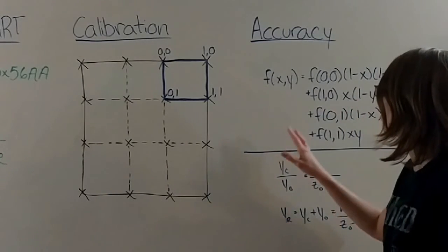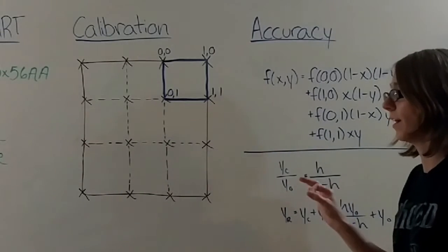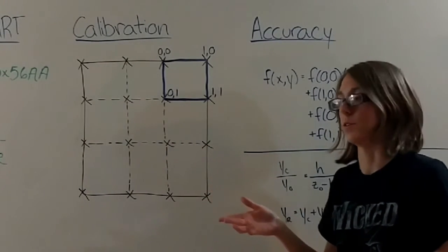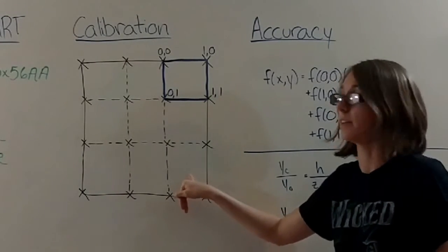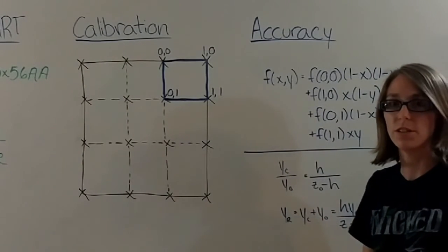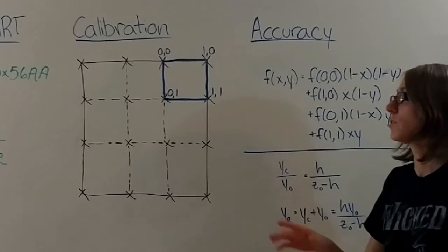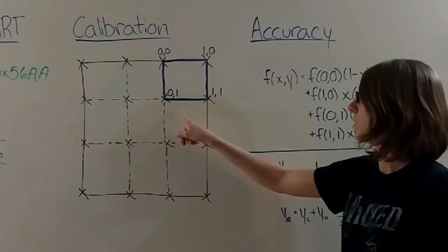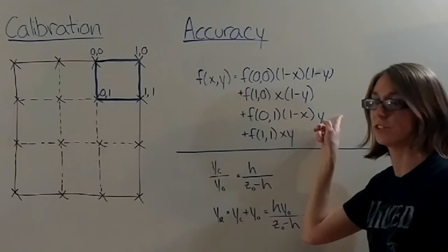Next, I use an algorithm to determine which block an object is in. So if an obstacle is in this block, then it's in block 9. The reason why this is useful is because I use bilinear interpolation, and that uses a unit square. So this is what a unit square looks like. It's (0, 0), (1, 0), (0, 1), and (1, 1). And this is the bilinear interpolation equation.